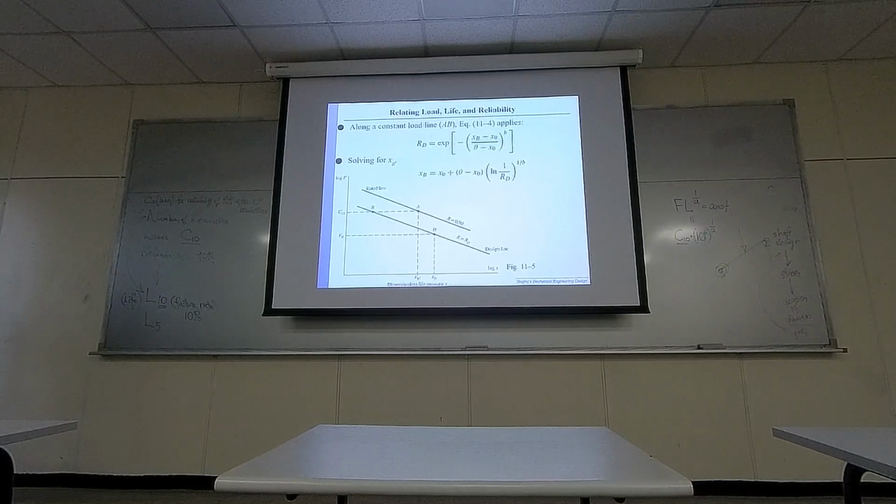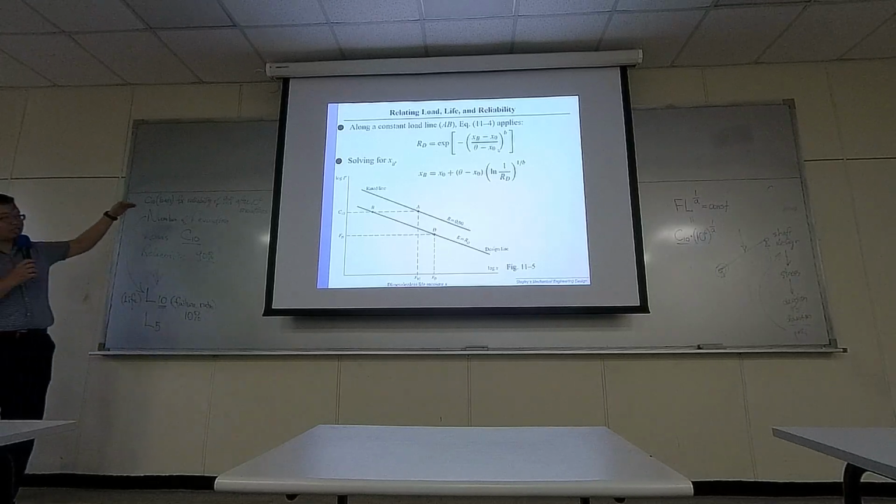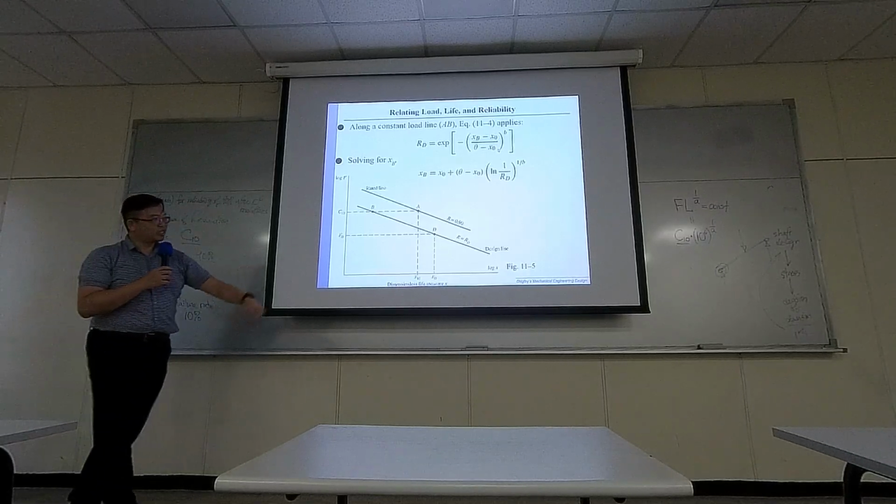Then what else? Okay, so for the point B, from point A, you can use the Weibull model. They use the Weibull model to estimate point B. See, from A to B, the relationship along this horizontal line is going to be described by a Weibull model where you see reliability gradually drops.